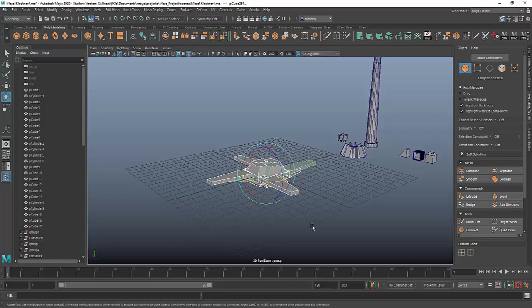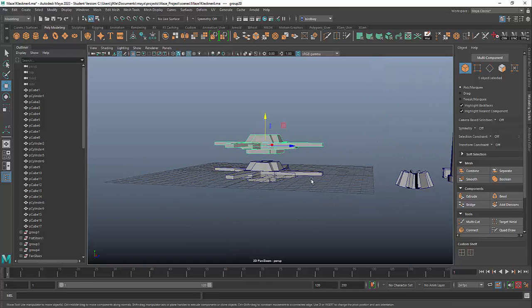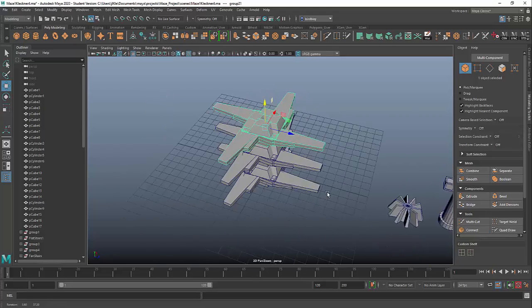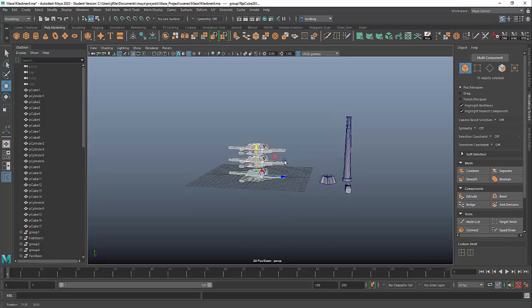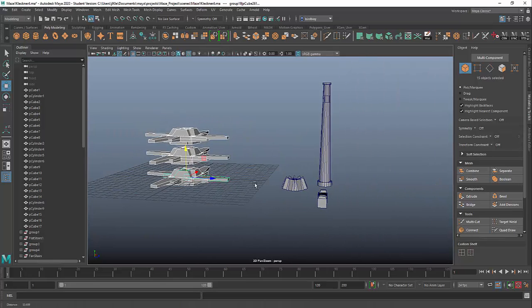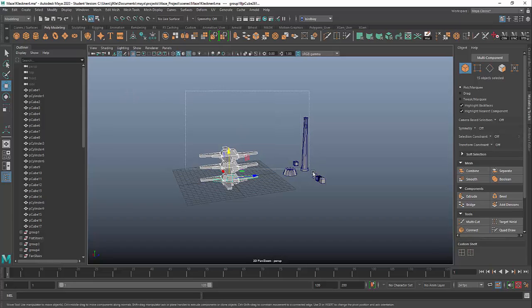Then you could group all of that by hitting Control G, and now this is one whole unit that I could duplicate. So you can see how you can start to create some really interesting form and geometry by working with multiples, right? All right, so I know that's a lot. That's just a little basic overview. Again, with objects, when you're trying to do some modeling, you're going into its individual components. And that's pretty much what you're going to be doing, having lots of fun with that.